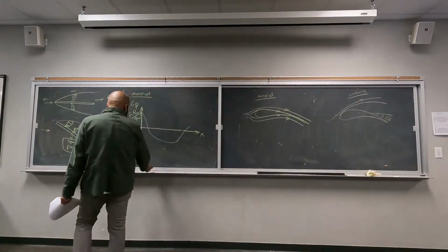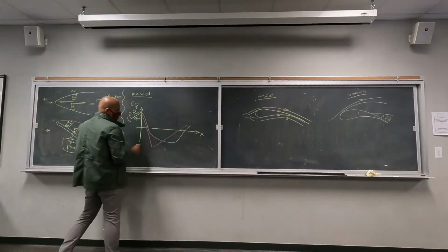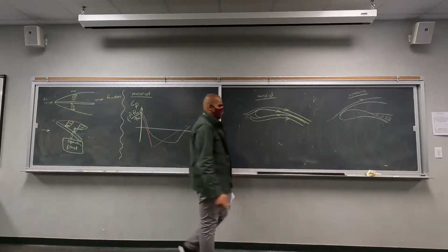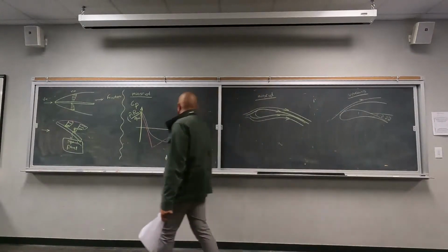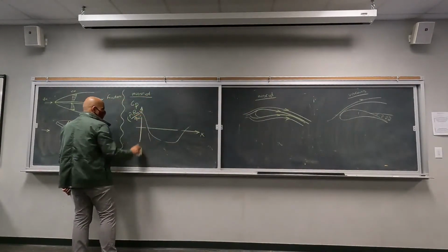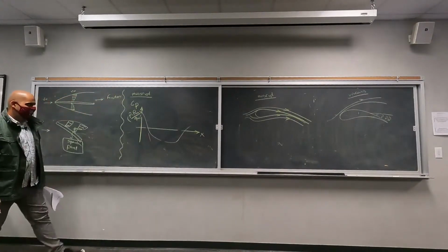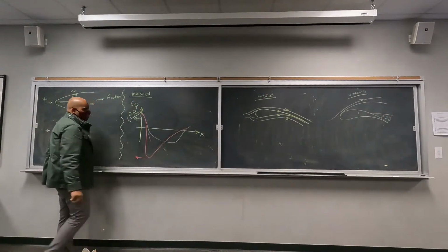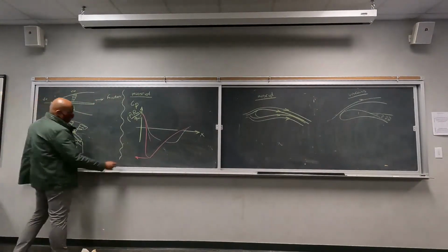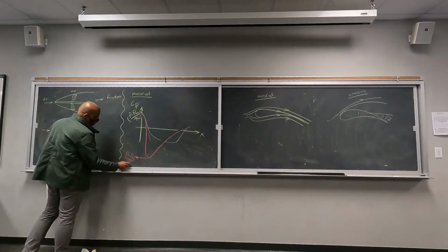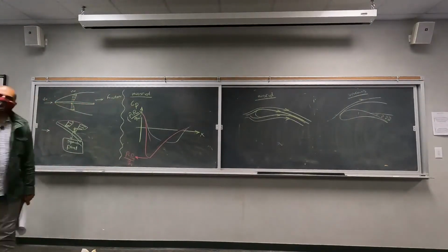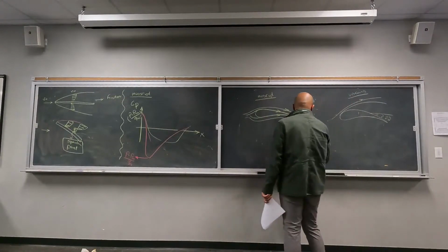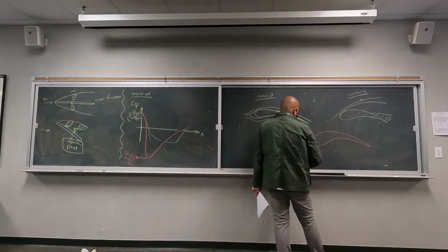Straight lines like this. I mean, it won't be straight, but what will happen is we will see some unrealistic values for pressure, right? So our pressure is going to look like this. A very, very huge drop in P minus P infinity, in the pressure coefficient. So we will see some unrealistic values for pressure coefficient. And what does it mean for the pressure distribution on top of the airfoil in terms of lift and drag force?